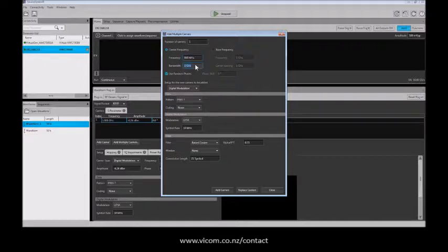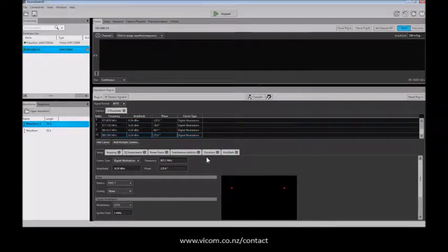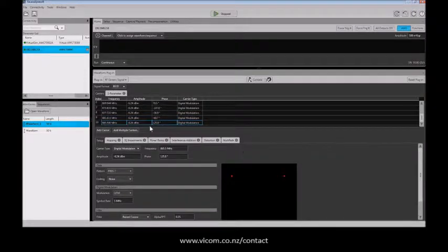And I set the bandwidth. The RSA507 has a 40 megahertz modulation bandwidth, so I will put this down to 35 megahertz. And I just say number of carriers. It could be, for example, 10. I think this is the QPSK. Symbol rate, yes, that's a good one. 1 megahertz is good. And I will replace the carriers. When I've done this, I've made 10 of these signals, and you can see each one of these can be controlled.